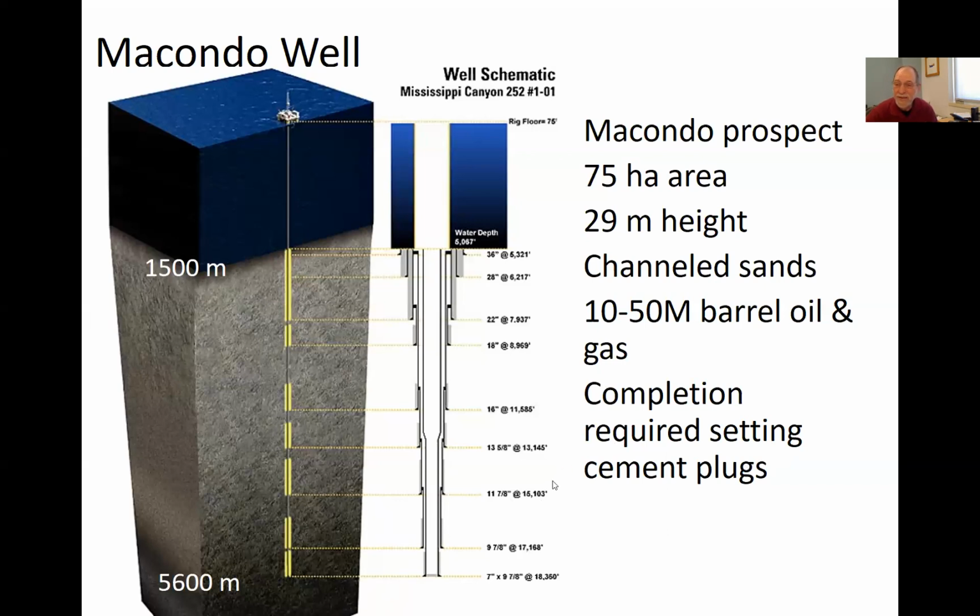But this really hadn't been done before. This was not the standard operating procedure. So they had to sort of invent a new technology. And they poured in cement, but they used a sort of nitrogen foam to try to foam the cement to have it fill a larger area. And so they foamed the cement, and they had rods that were supposed to position the plug successfully, that they were in place.